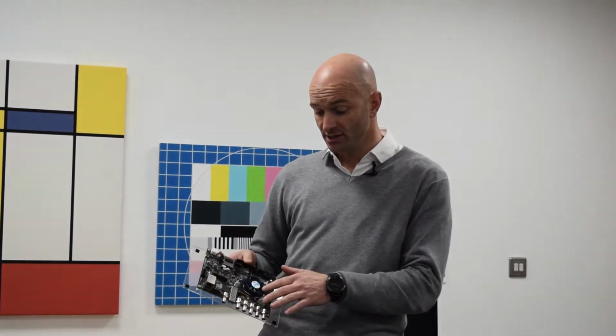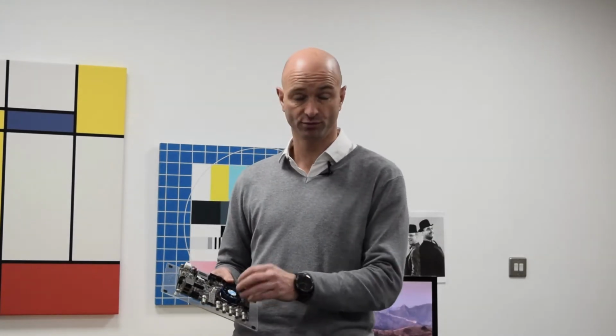It should be noted that this is actually a reasonable size FPGA here, and our Warp IP only uses a small fraction of this, so we can run in smaller, lower power parts. During this demo we'll be running the Warp at 4K 60, but we can produce smaller IP for smaller footprint parts, for example 1080p HD video, but we can also extend the Warp IP to run up to 8K video at 120 Hz. So in this next section I'll demonstrate the operation of the web page control